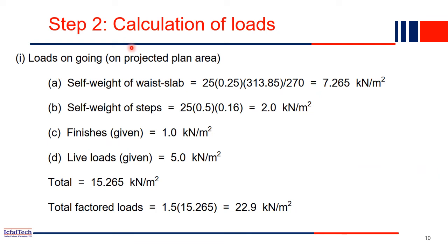So now step 2 is the calculation of loads. It is a similar thing to what we did in the beam design also. First we computed the effective length, and then in the next step we do the calculation of load. Then in step 3 we do the calculation of bending moment and shear force. Then in step 4 we find out what reinforcement is required. All the processes or steps are the same even for the slab design as well.